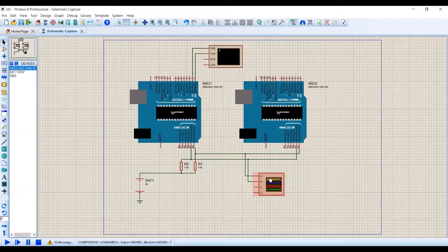If you have an oscilloscope, you can check the address that you've written from here and goes in the line, and if the line has some kind of oscillations and everything, there could be some troubles or electromagnetic interference. The data will not be transferred. Everything can be seen using this oscilloscope. I'm talking about real life. And sometimes you have to adjust these resistors in order to achieve the commands if there are some issues in these two lines.